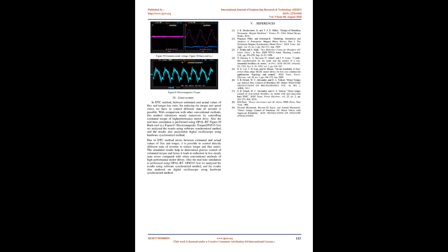First we analyzed the results using the software synchronized method, and the results were also analyzed on a digital oscilloscope using the hardware synchronized method. Due to the DTC method's errors between estimated and actual values of flux and torque, it is possible to directly control different states of the inverter to reduce torque and flux errors. The simulated results help to determine precise control of estimated torque, and hence lead to a reduction in steady-state errors compared with other conventional methods of high-performance motor drives.